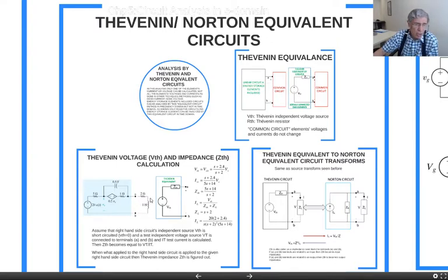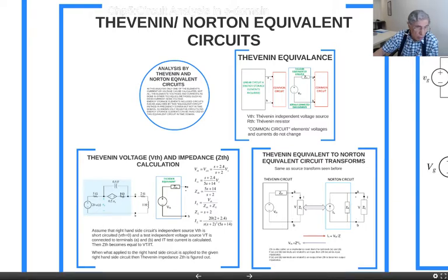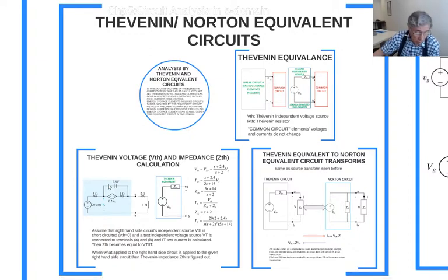And we are going to calculate this load impedance, current and voltage only, not the other elements, current and voltages. These blue area elements, current and voltages cannot be calculated by this method. You've got to use general analysis techniques if you want to do so.